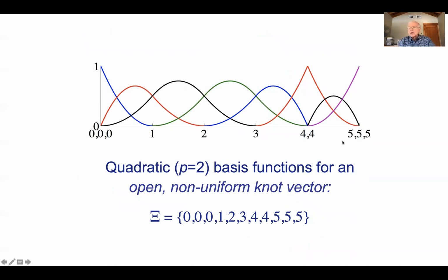You can start with sort of a uniform distribution of knots. But if you have multiplicity p+1 at the ends of the patch, you become interpolatory there. So the value of the function would be 1. You can repeat knots. They don't have to be equally spaced. You can also repeat knots, though. And when you repeat a knot, you lower the continuity by 1 degree.